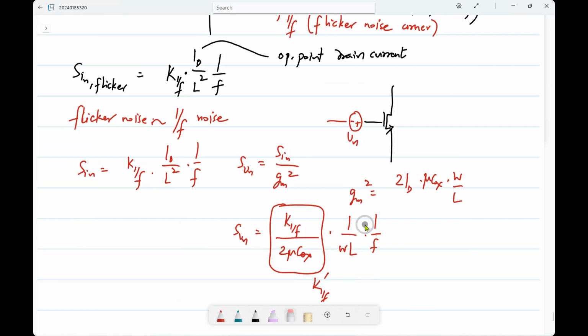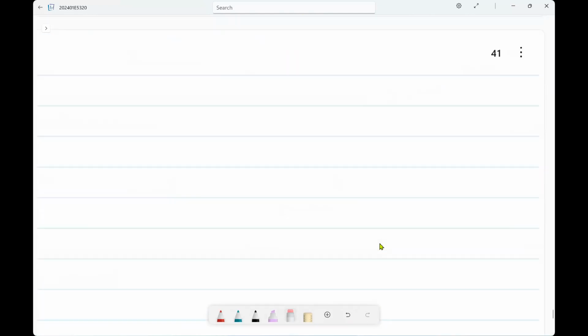Any questions about any of these? So as far as we are concerned, we only need to know the models. For every component, you can either refer it as some current or some voltage. This is true of mismatch. This is true of noise. And you need to know what the spectral density is of each of these noise sources. And then you have to be able to calculate the transfer function from this noise source to the output quantity, whatever that is. Okay. So we can go through an example calculation.